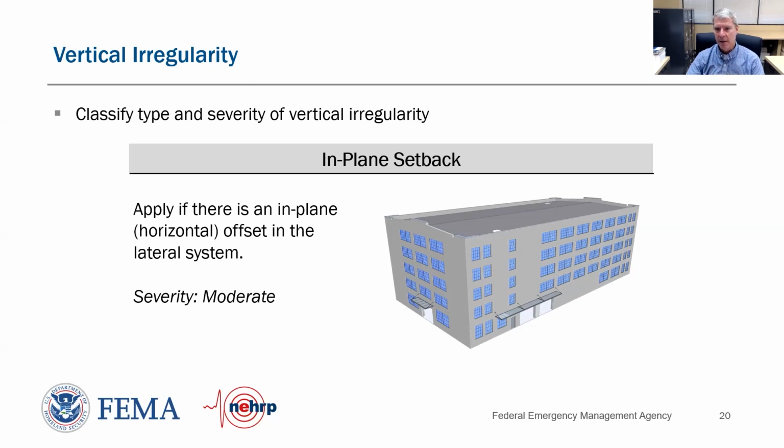We can see it much more than the windows in the other section. But when we land on the first floor of the building, it lands on two openings with just columns and beams, no shear wall. To the right of those two openings is a nice long shear wall, but it's offset in plane of the wall.